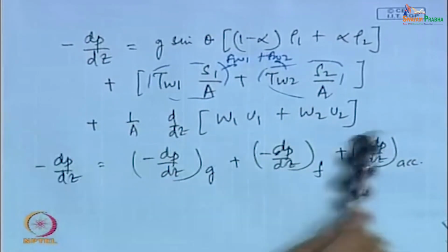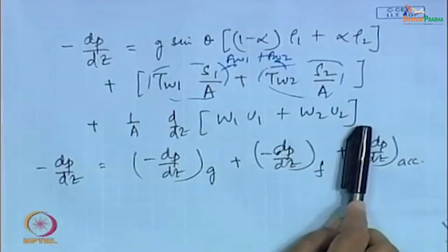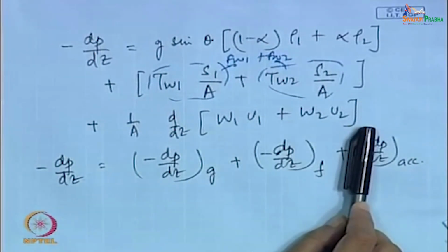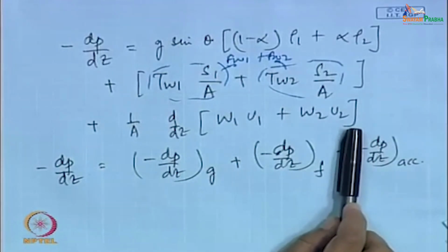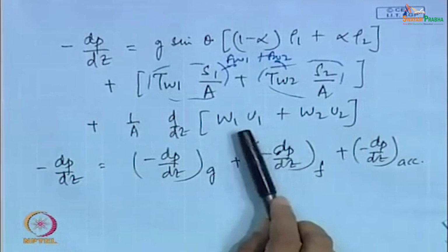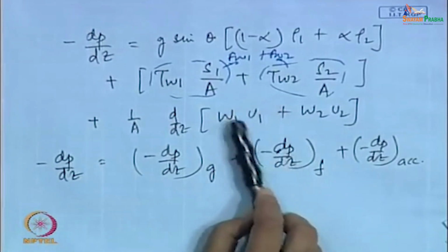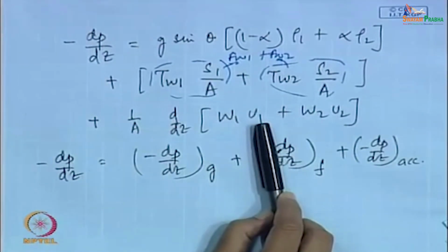So, therefore, we do not have a tau I in this particular expression. Now, once we have got this expression, the next endeavor is how to find out the pressure gradient from it. Just as we had done in the previous case for homogeneous flow, we find that U1 should be varying with Z. Why? Because the specific volume, or the density, varies with the axial distance just because of the pressure drop.